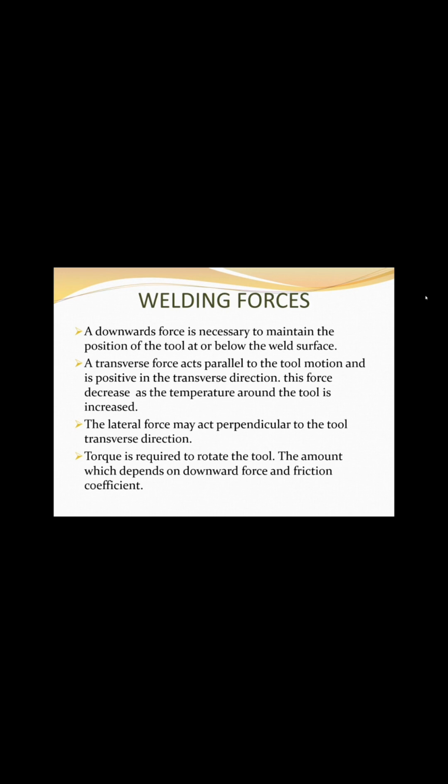Next, coming to the welding forces. A downward force is necessary to maintain the position of the tool at or below the weld surface. A traverse force acts parallel to the tool motion and is positive in the traverse direction. This force decreases as temperature around the tool is increased. The lateral force may act perpendicular to the tool traverse direction. Torque is required to rotate the tool, the amount of which depends on the downward force and the friction coefficient.